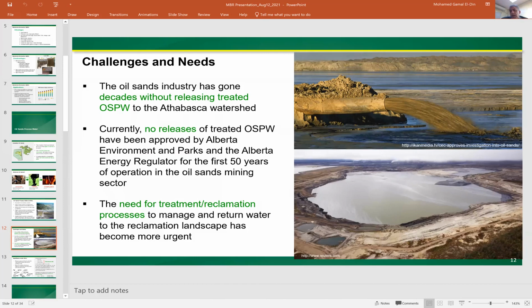In those tailing ponds, the liquid or the water is separated at the top as a supernatant with some residual solids and organics and salts. And that supernatant at the top is recycled back for reuse, for extraction. So we keep recycling this water many times, sometimes as many as 80 times for extraction. And once the TDS levels or the chloride levels, among many other things, have reached a high level that can interfere with the extraction process in terms of the efficiency, this water is no longer used for the extraction and is stored in recycle water ponds. It is stored for now.